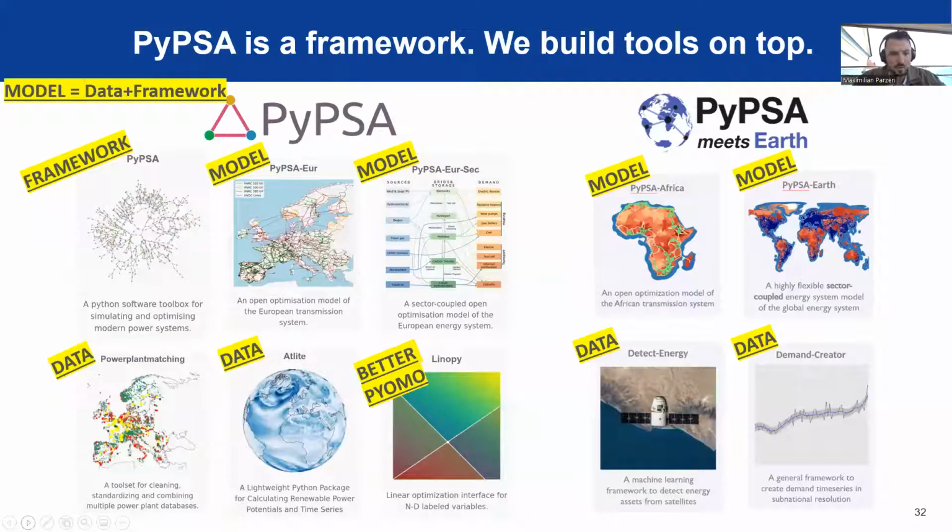So there's also, in particular on the supply side, where the PyPSA community works a bit. We are matching power plants in Europe across different databases, so it's like a data fusion task. We also have renewable supply estimations all across the world, and dynamic line rating constraints that are calculated depending on the weather, and then also a Pyomo alternative for the specific energy optimization part. And that's really just the PyPSA part, which has been continuously developed over the last 5 years.